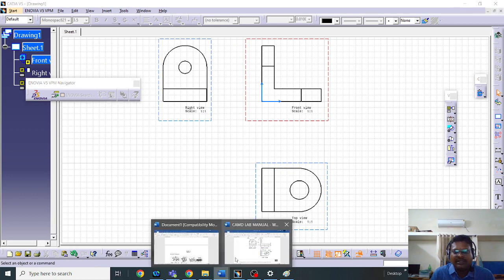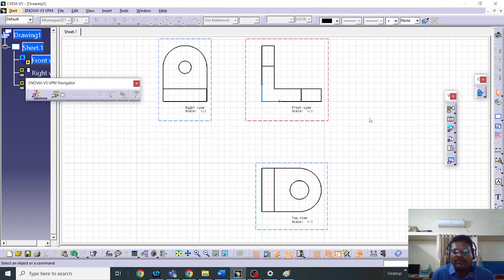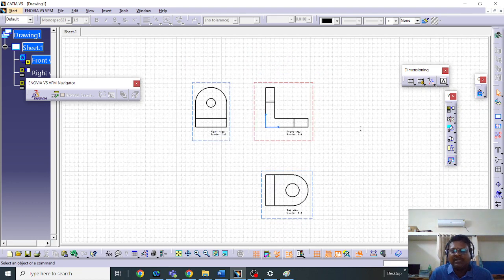If I look clearly, I can have some dimensions with respect to the given member. For dimensions, a separate toolbar is there. Just hold shift on your keyboard, it will tilt. With this dimension toolbar you can give the detailed dimensions of your object. Whatever dimensions I've given to the structure can be given, and that is also possible in this drafting itself.